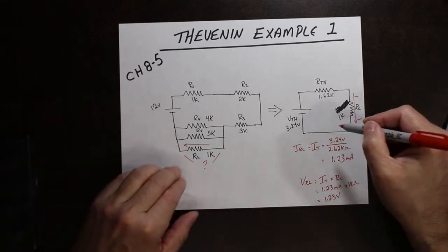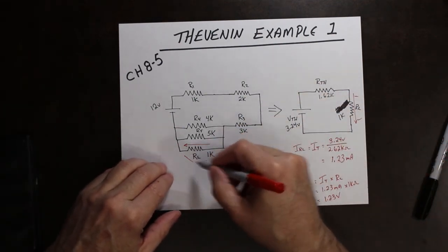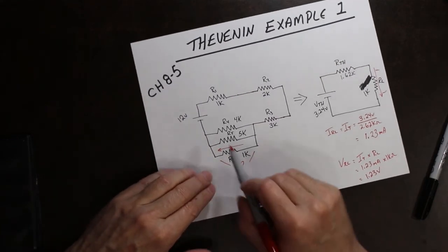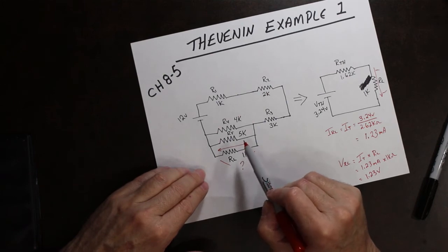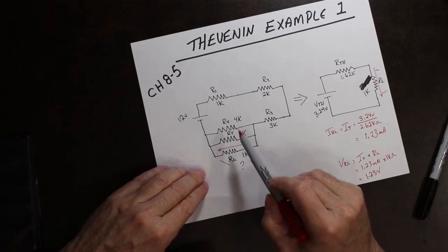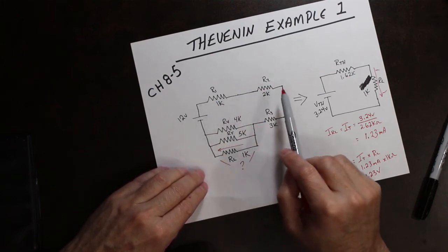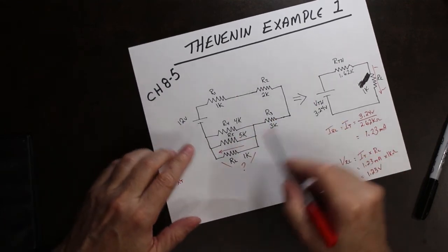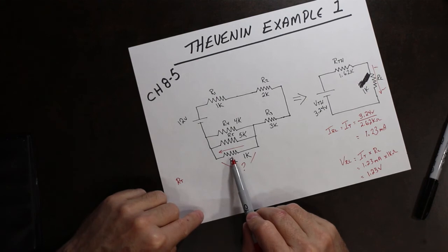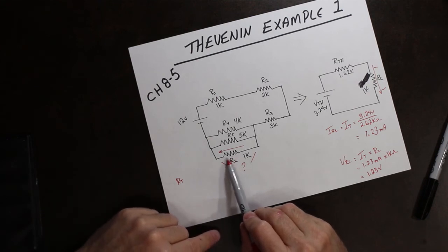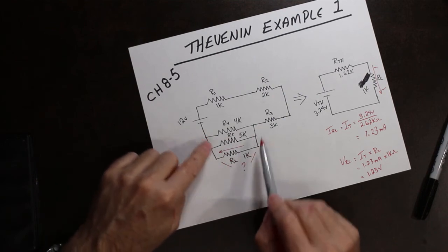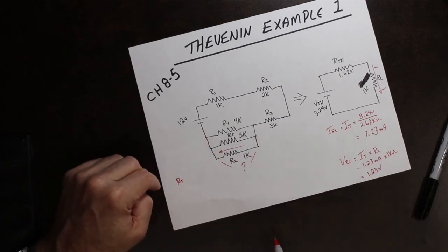In order for this to be true, I must get the same calculations on this circuit. So on this circuit, I am going to figure out R total of that whole circuit, and then figure out what current is going to be flowing through here or what voltage is going to be across this whole network, and they should match.